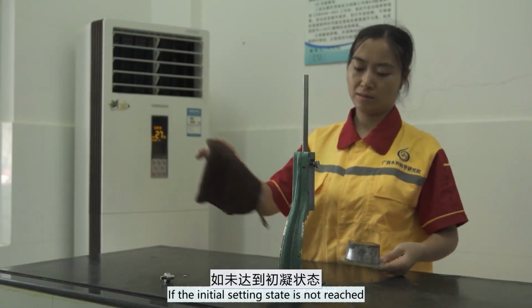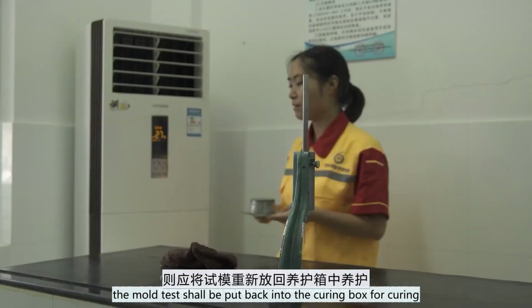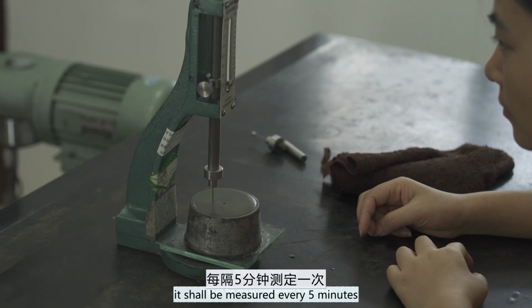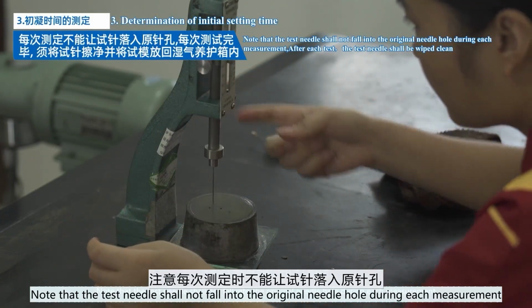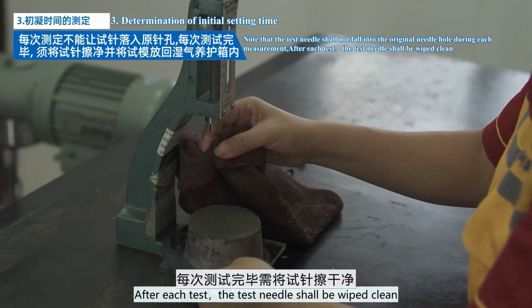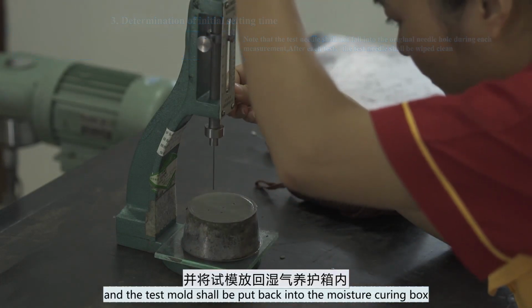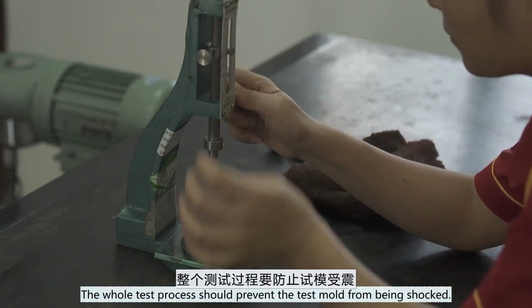If the initial setting state is not reached, the test mold shall be put back into the curing box for curing. When the initial setting time is approaching, it shall be measured every 5 minutes. Note that the test needle shall not fall into the original needle hole during each measurement. After each test, the test needle shall be wiped clean, and the test mold shall be put back into the moist curing box. The whole test process should prevent the test mold from being shocked.